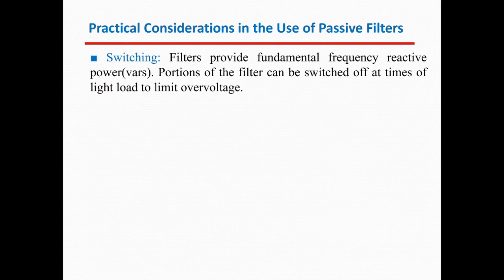harmonic. Switching. Filters provide fundamental frequency reactive power. A portion of the filter can be switched off at times of light load to limit the overvoltage.